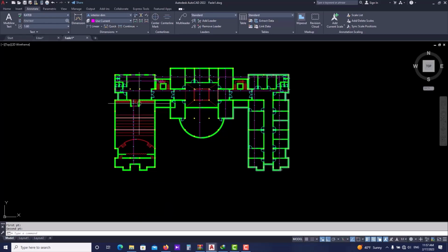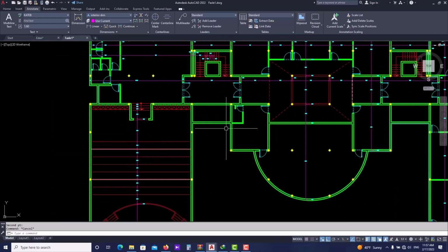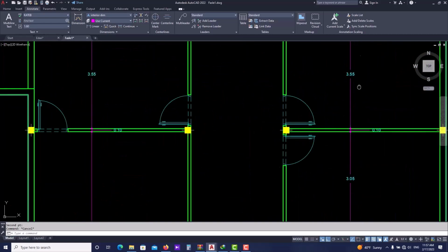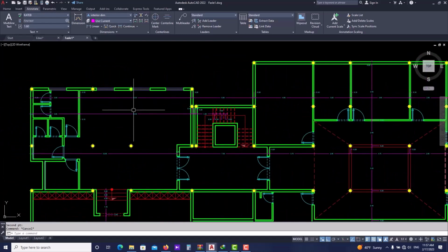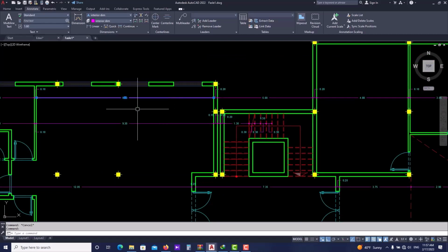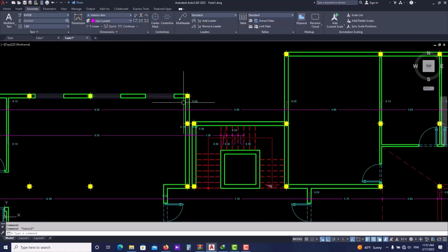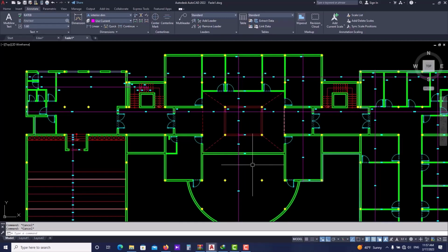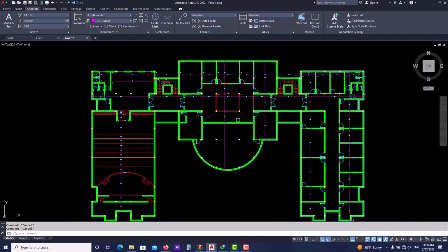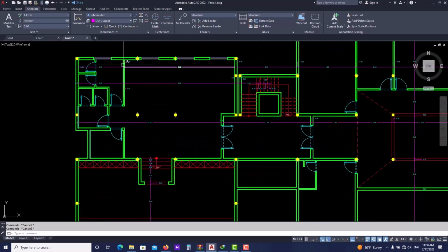So, overall, as you can see, this Lisp, this technique can help you get on with your work, to set your dimensions, for example, extremely faster. And remember, it works based on the last settings that you have set. So if you change something up here, for example, AutoDime would work based on this again. So remember, you should pay attention to all of the settings and items that you activate or deactivate, or some settings, for example, like scale and size, before you start working with AutoDime.